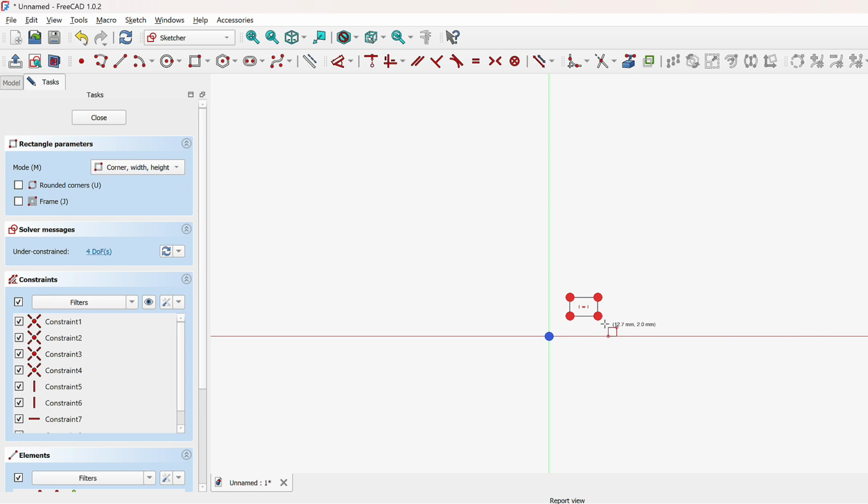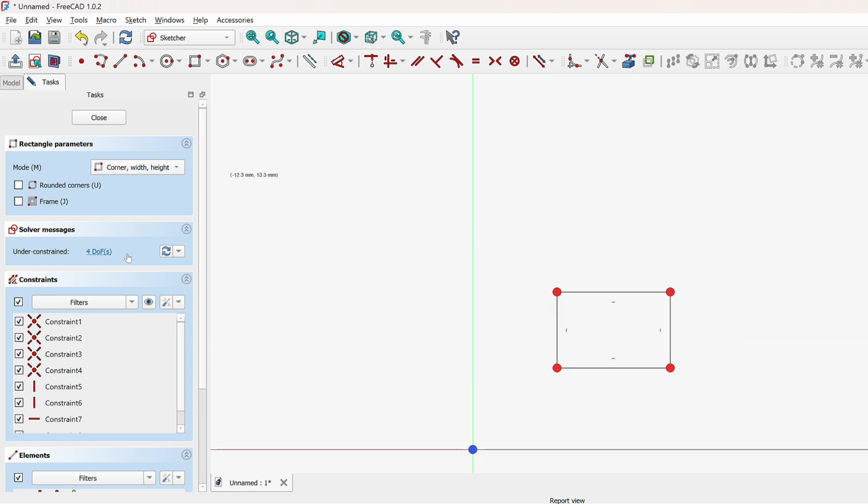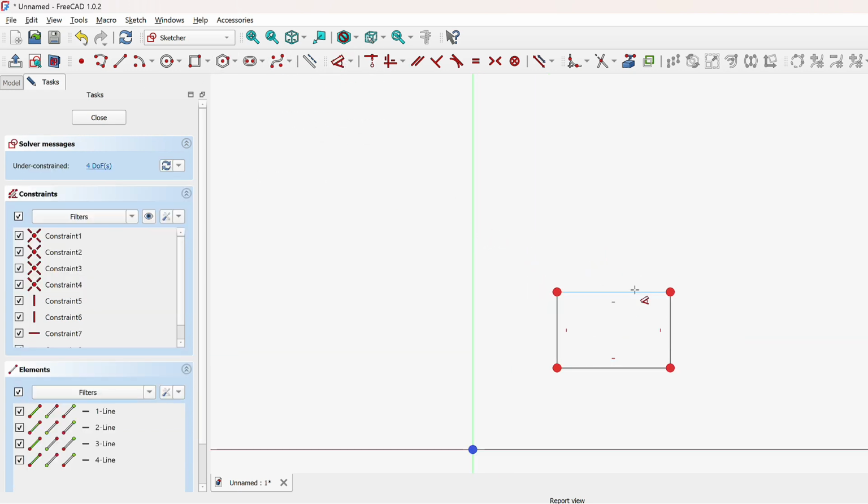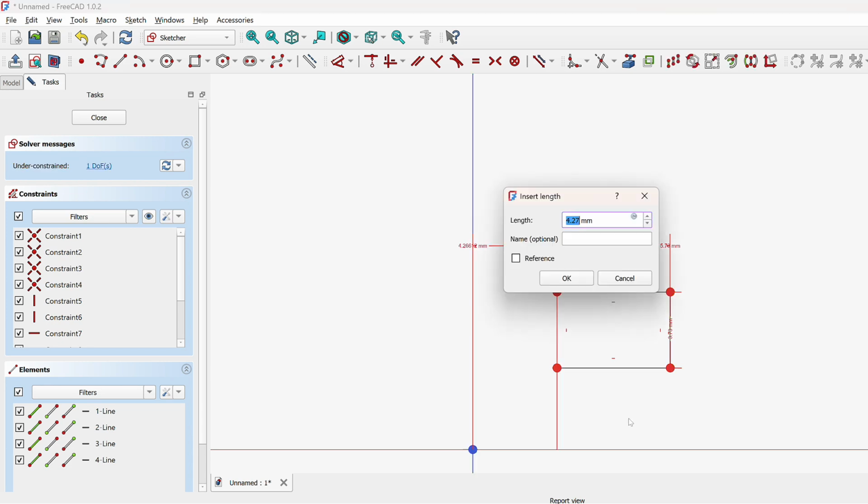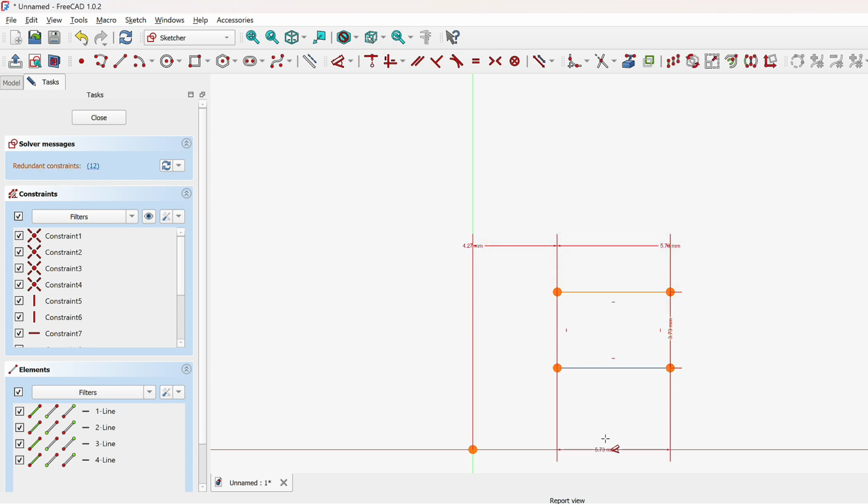Let's say the geometry is this rectangle, and let me constrain it. I'm going to apply horizontal as well as vertical dimensional constraints, and I'm going to keep the dimensions as they are because my intent here is to show you how we can use the array transform tool.